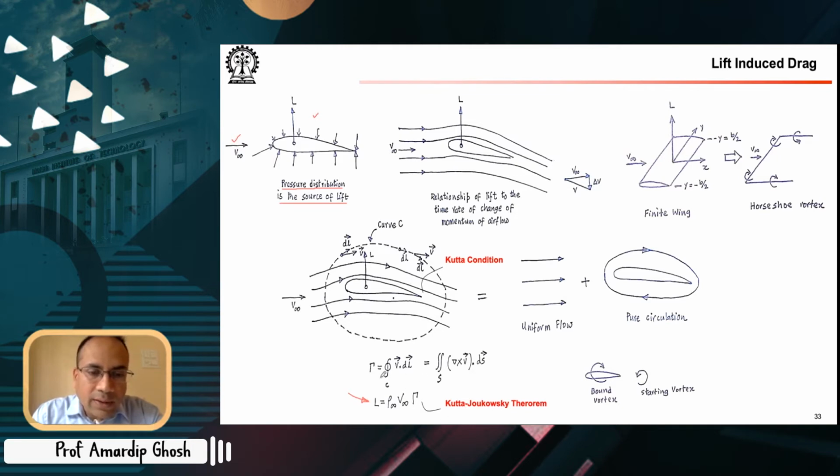So the circulation theory of lift is primarily used in the low speed incompressible flow regime. In case of supersonic flow fields, we use shock expansion theory and other approaches to justify the pressure distribution. Here we don't have shock waves, so it's all about fluid acceleration and deceleration. Essentially, the velocity of the flow creates the pressure distribution, and that is explained through the circulation theory.